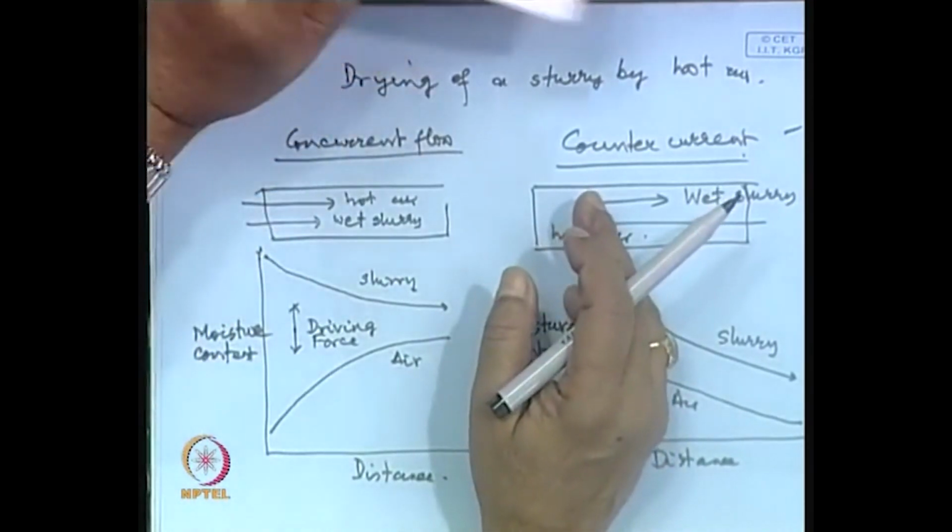This is the basic principle also in the case of counter current flow of slag and matte, because we want matte and slag to react and ensure that any copper in the slag phase goes into the matte phase. How will it go? One of the ways, as I have mentioned, is FeS will react with any Cu2O in slag, form FeO in slag, and copper will be recovered and it will go to the matte phase. So, we need a counter current flow of metal and slag, and for that some simple engineering techniques are employed.